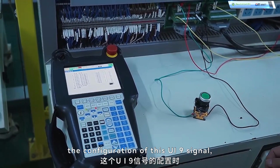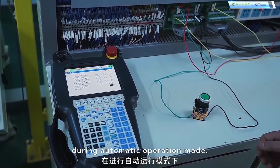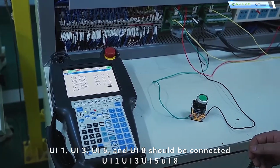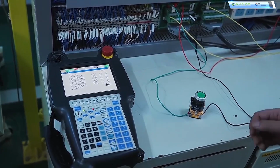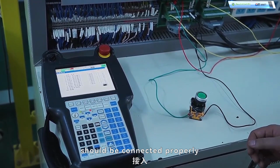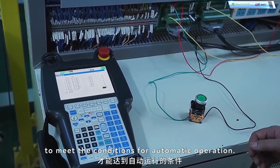When completing the configuration of this UI9 signal, we must ensure that during automatic operation mode, UI1, UI3, UI5, and UI8 should be connected according to normal safety standards. The corresponding sensor signals and switch signals should be connected properly to ensure these ports are in an on state to meet the conditions for automatic operation.